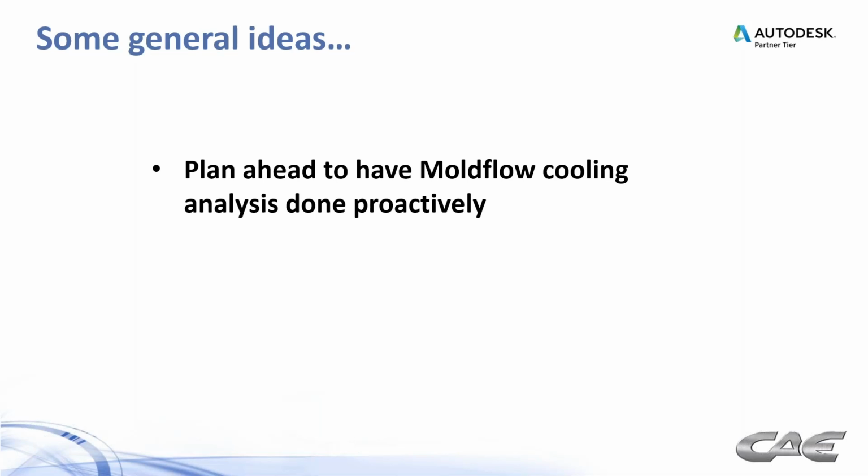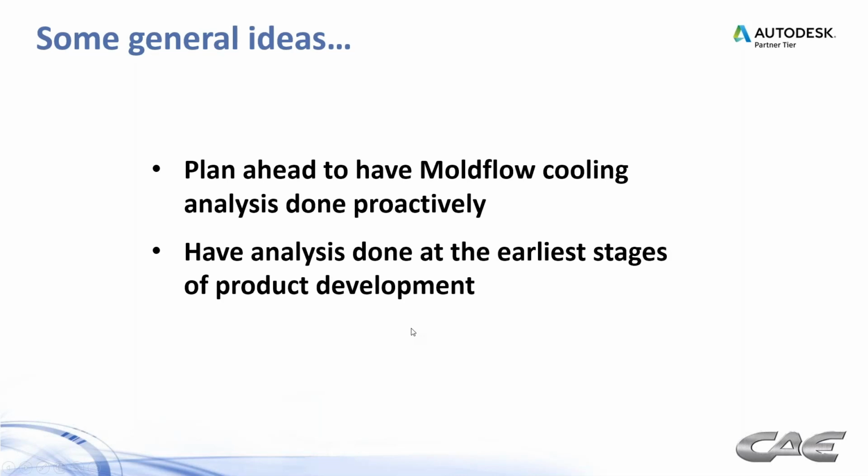If you have say in that cooling design, you should be talking about Moldflow on every one of them. And again, have this done at the earliest stages of product development. If you're waiting too late, there's not going to be any time to try a bunch of different scenarios out, much less get them implemented.